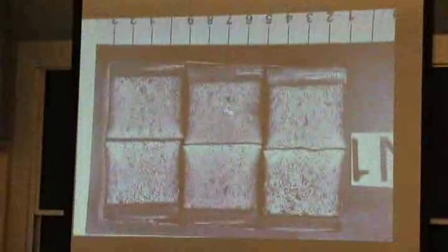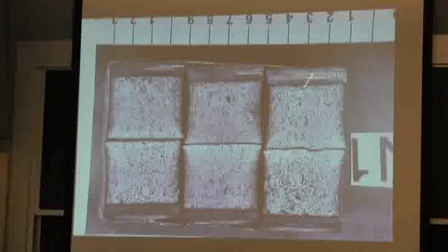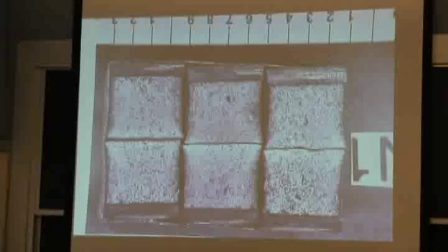These are some of these same steels from this particular failure at this other gas compressor station in Texas. And some of them were very brittle. You take a 1 centimeter square bar of steel that's 10 centimeters long, and we're looking at the fracture surface. You put a very precise 2 millimeter deep notch in this 10 millimeter square of steel, and then you hit it with a hammer. And you measure the energy dissipation in the hammer.